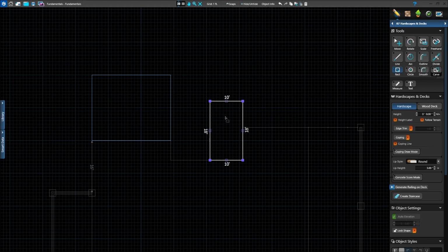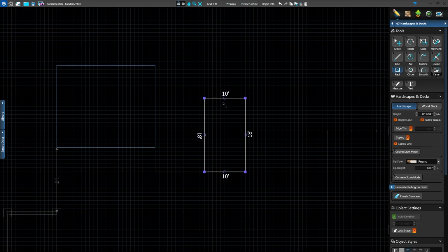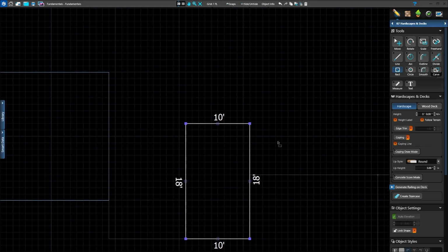So because there is a slope, we need some stairs coming up to this walkway, and we'll also add some handrails. And in order for this to work correctly, I'll draw my handrails first, and then I'll add the steps so that the steps fit in between the handrails. And these handrails are kind of neat. They have a decorative element to them. They come out and they curve around. So this is going to give us a great opportunity to work with the arc tool. But we're going to start with the line tool. Go ahead and activate your line tool. I'm going to draw one of the handrails, and then I'll use a method for copying and pasting so that we don't have to draw it again on the other side because they're identical.